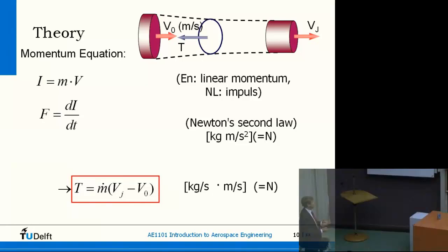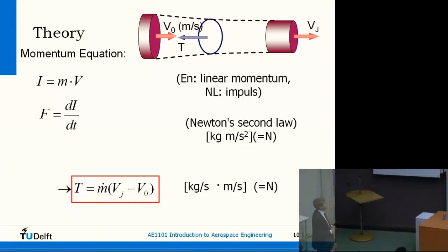It's the change of mass per second. And in terms of the engine, it's not really the change of mass, but it's the mass flow. So the thrust can be calculated simply as the mass flow times the difference in speed. And so if we get a larger speed or a larger mass flow, these are the two ways to increase the thrust. And this is, of course, the conventional way we write Newton's law.